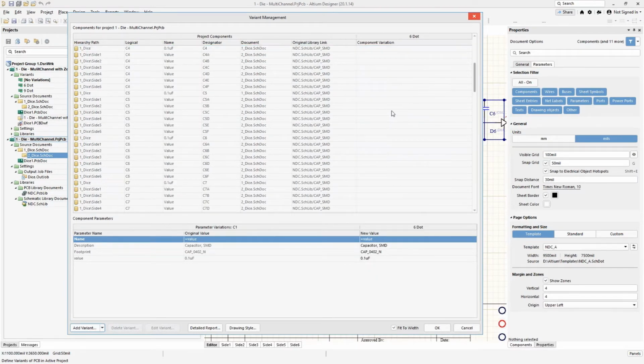Now, what can I do with it? By default, everything here has been fitted. So I have the option of either unfitting something, or creating an alternate part. Let's do the easy one first. Let's simply unfit a part. Remember, I've got to get rid of the C4 capacitors, which there are on multiple sides, because it assists with the LED, and I don't want the LED, so I don't need the capacitor along with it. You'll notice over here that there is a C4 as the die itself, and then they have each of the sides.